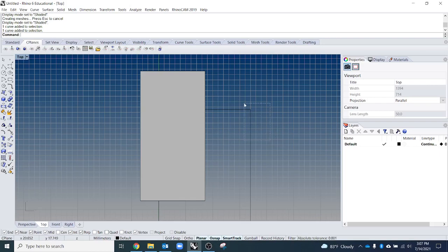And the way that we're going to line weight our drawing will actually be through the layers when we do our 2D drawing. If you don't see the layers panel, down here at the bottom where it says default, that means that we have the default layer set as current. Right now, that's the only layer in my file. I could make a new layer by clicking the little new layer button, and I could name it whatever I want. I could call this my rectangle, and I could call this my cube.